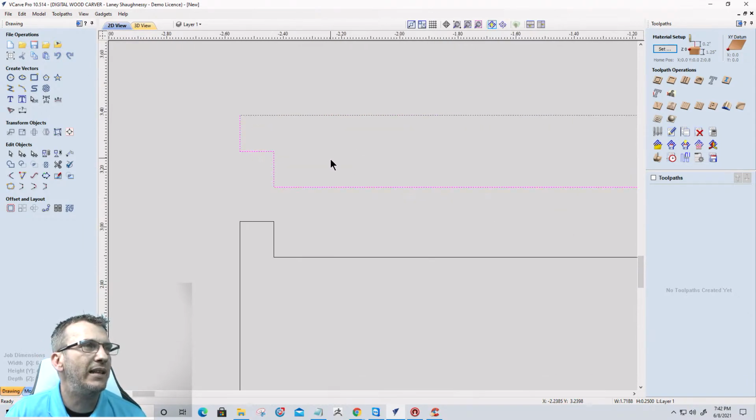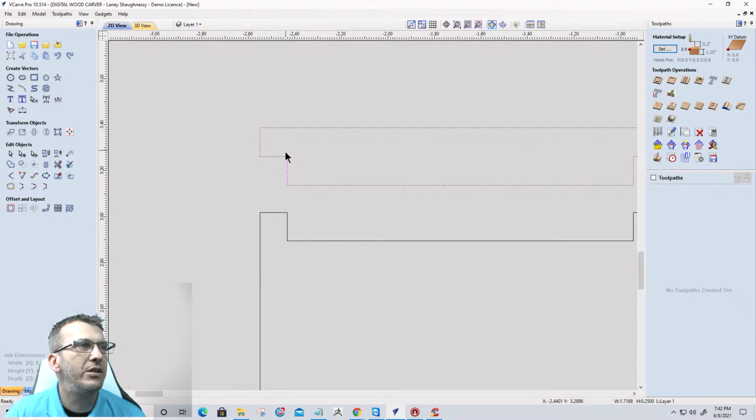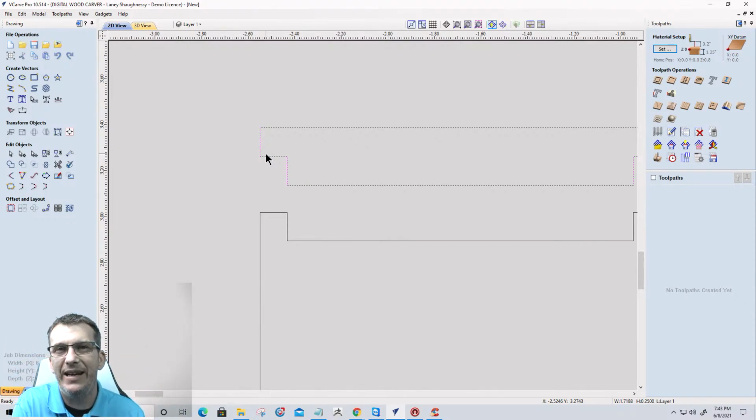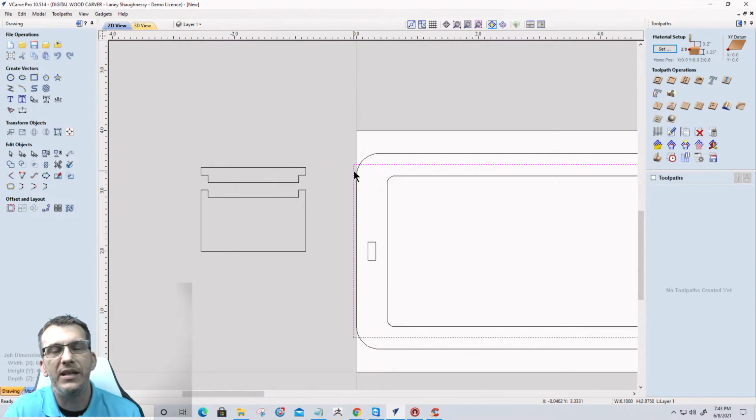So let's imagine that this is my lid here. I would like the lid to be an overall height of 3/8 of an inch. I would like at least a minimum of 1/8 of an inch thickness to 3/16 of an inch. So maybe half and half, right? And for me, a little bit more, because I want to be able to round over the edges when I break the edges with the sandpaper and everything. I want a nice edge on the top of that lid. So I'm going to go 3/16 of an inch and 3/16 of an inch for a total of 3/8. So I'm going to split that lid. What I need is my pocket cut here to be 3/16 of an inch deep. Okay, 3/16 of an inch deep.